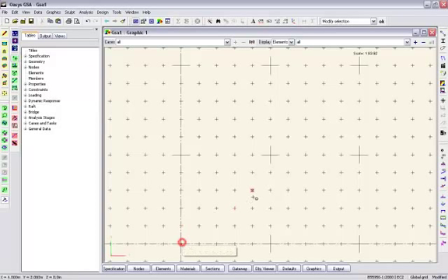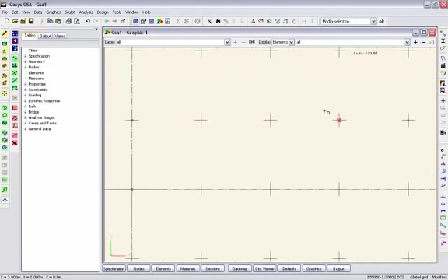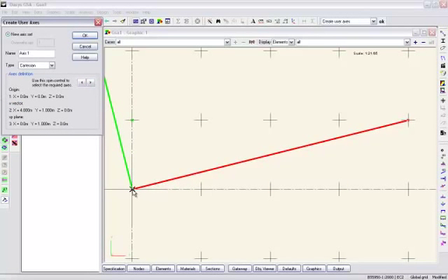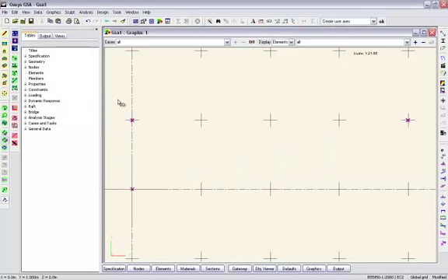And I'm going to create an axis just by creating a 1 in 4 slope to begin with, and then an additional point just to set that up. And I'm going to select those 3 points, and I'm going to use this create user axis, and that's what I want. X is a 1 in 4 slope on plan, and Y in that direction, and let's call that axis deck. And then I can delete those 2 points there.